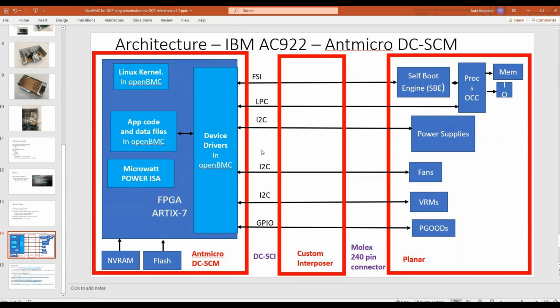Okay, Casper, is part of the DC-SCM 2.0 plan to provide reference designs for that interface in the form of RTL that people can grab and go? Yes, that's the plan, absolutely. I think the interesting point would be the integration of this interface entirely in the BMC SoC, in this case the FPGA, without any additional interfaces connecting the BMC to the CPLD as a bridge.